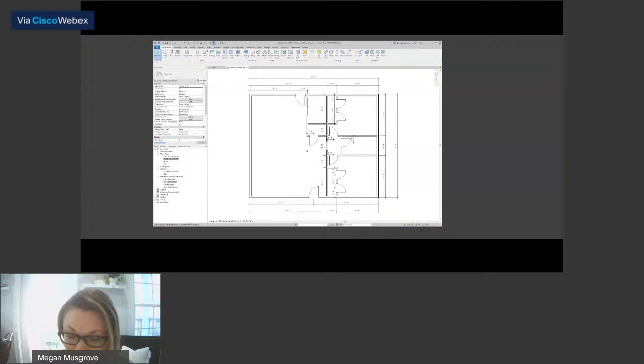Or there is another way, and sometimes this comes in handy if you had like a second floor with a balcony or something like that, and you actually want to see that edge and you don't want to mess with detail lines, I'm going to show you another way. We're going to go Control Z to put it back. So if we hover, we've got that one again.